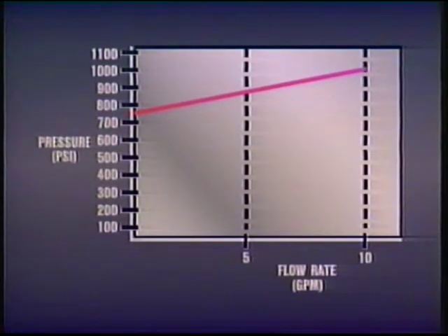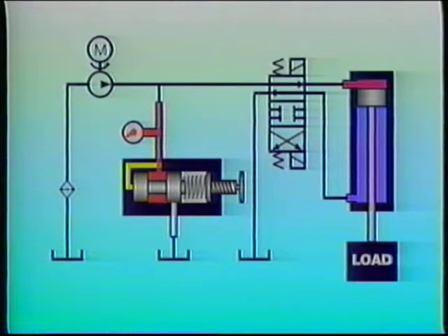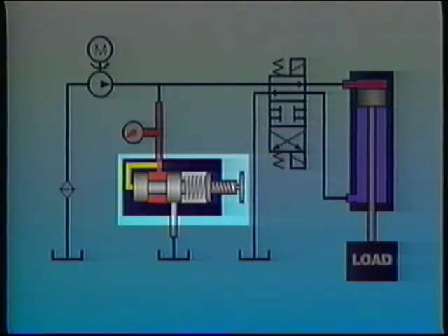Therefore, the cracking pressure of a relief valve must be taken into account when a particular flow rate is important to the proper operation of a system. For example, the relief valve in this system is set to open at 1,000 psi.